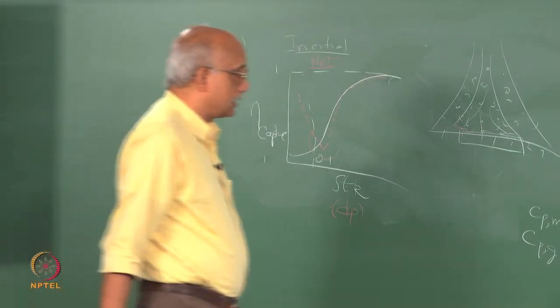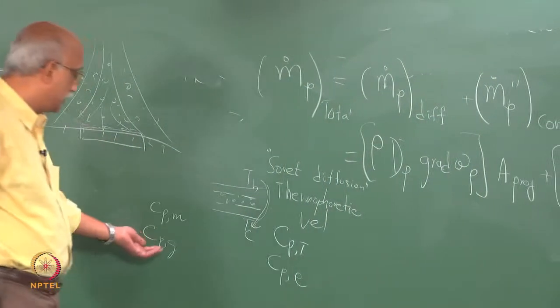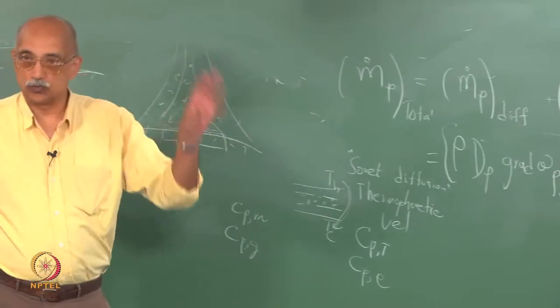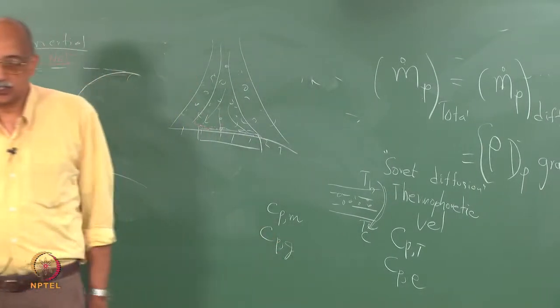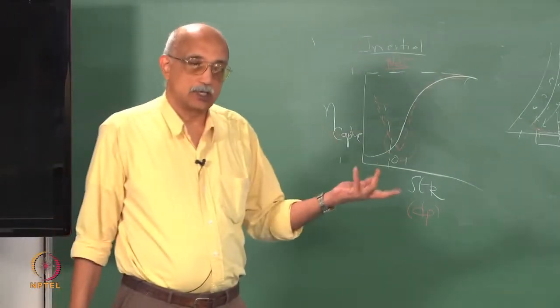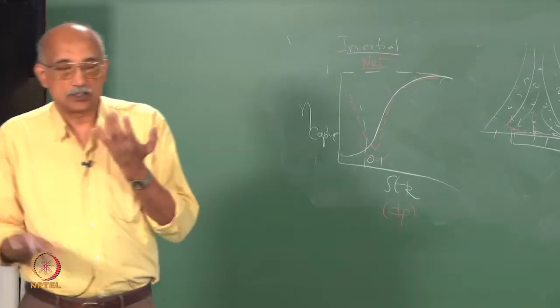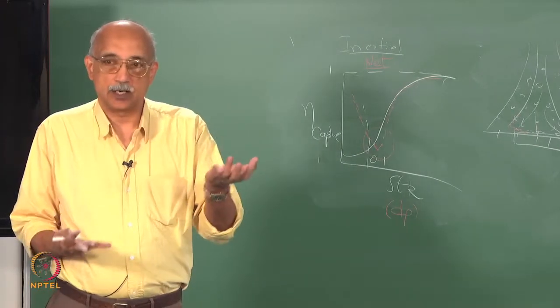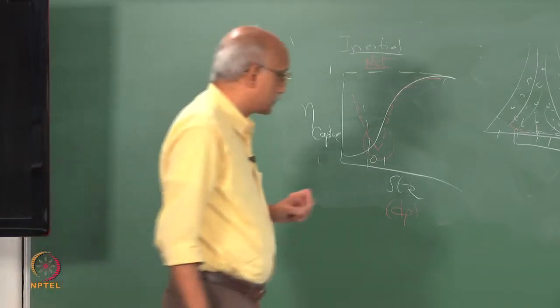So, again, instead of considering this as a separate field, you can club this into the phoretic field, and so Cpg will be simply the velocity, typically the terminal velocity, that is associated with a balance that you achieve between a gravitational field and a drag field that the particles are exposed to.